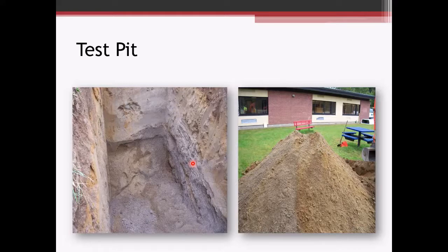So one of the things that we'll look at if we're looking at soil bearing capacity for a project at this elevation, typically the engineer is going to take a discrete sample from this location to evaluate that material. Whereas if we're looking at a material to be used as backfill for a foundation wall, it may make sense to sample the material here because once the material is excavated, it's all mixed together, and this is the material that's going to go back in as foundation wall backfill.